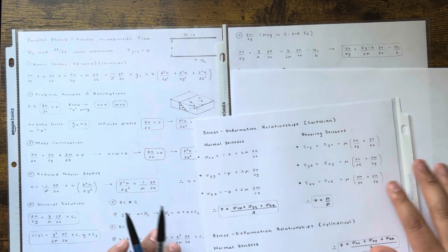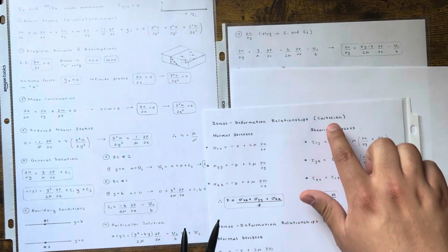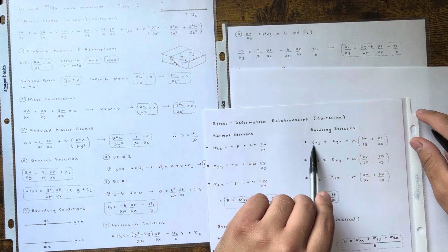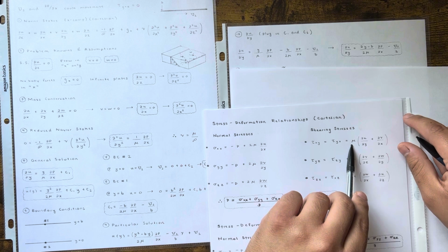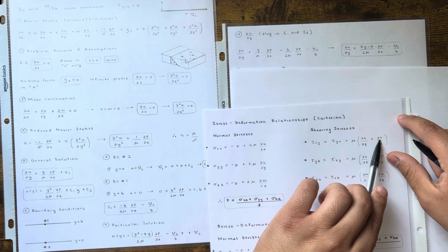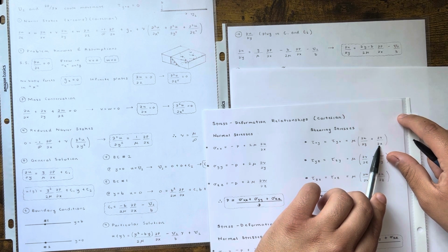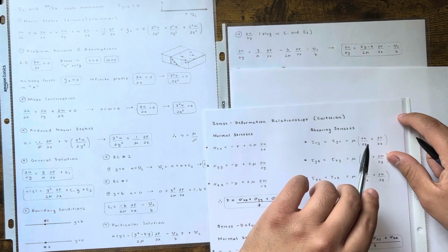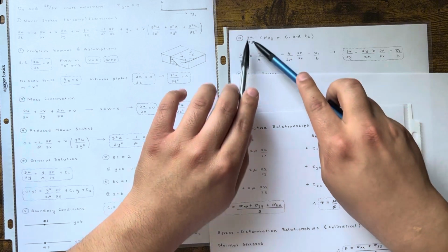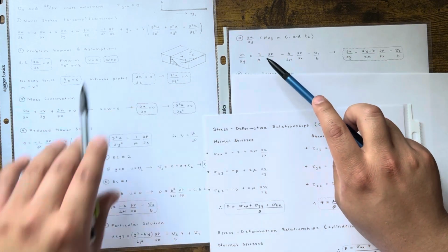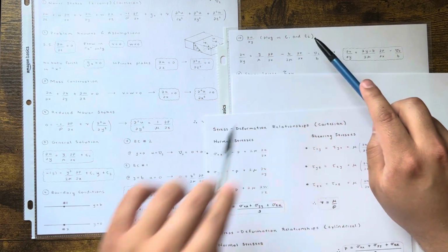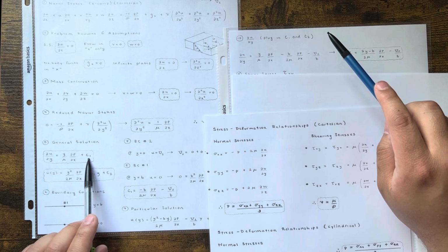So this is the shear stress in the Cartesian system. The Cartesian system for shear stress says tau xy is equal to mu times the gradient of the x velocity with respect to y, plus the y velocity with respect to x. Well, guess what? Before I continue, let me just continue this step. To get the delta u over delta y, all you need to do is use this and plug in the C1 that we found. You should plug in C1 and C2, but in this case there is just C1.